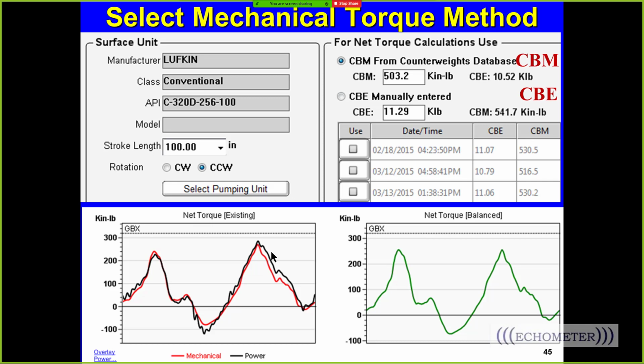So Anthony, based on your previous comments, people should stop using amps. Yes, we have seen a lot of difference. Just looking at a screen blinking about half a second apart has a very low sampling rate. When you compare that to a chart that you're acquiring at least at 30 hertz, of course you have more data points and you can check torque peaks and current consumption much better than on a single screen. Of course, it's much better to do it with these kinds of devices.